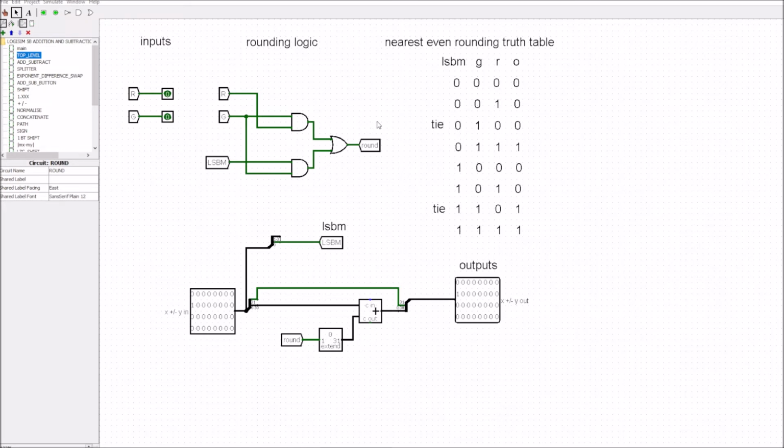So this will tell us whether we have to inject a rounding bit or not according to this truth table. And we would inject the rounding bit here at the very beginning. So what we're going to do is we're going to have a rounding bit, this is this bit here, and it's going to be an addition on to whatever we have here. So we're just adding 1 onto this number here. So the 1 will come in here and it will ripple all the way through. So it doesn't actually ripple all the way through because we don't want it to ripple through to the very top one, because the very top one here is our sign bit. So we set this up so that it will ripple through for up to the first 31 bits, and we take the 32nd bit here, which is the sign bit, and we just bring it back out and we put it back in here. So that means that the round bit only ripples up through the first 31 bits, and that will give us the final output here.